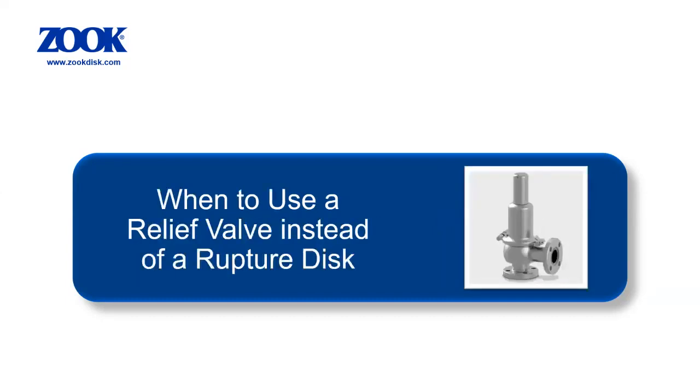Notwithstanding the benefit of the disc, there are many cases where a relief valve is actually the preferred method of pressure relief, and we are the first to acknowledge this. The most common would be in processing or continuous service applications, where downtime is a problem. A valve will typically reclose after relief, whereas a rupture disc would need to be replaced prior to a restart. However, there is a way to get the benefit of both the disc and the valve by installing a rupture disc directly upstream of a safety relief valve.